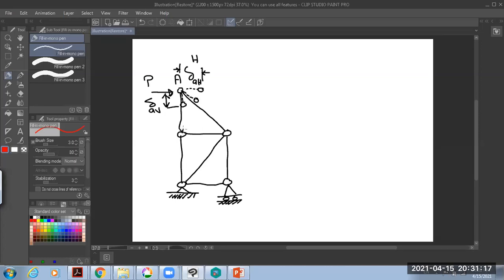So this member will be deflected in this direction, and this member will be deflected in this direction. You can calculate horizontally only, and you can calculate vertically only. In the end, you take the summation of them and take the resultant. That means this free end joint can deflect in two directions, the horizontal and the vertical. So this is case number 8.